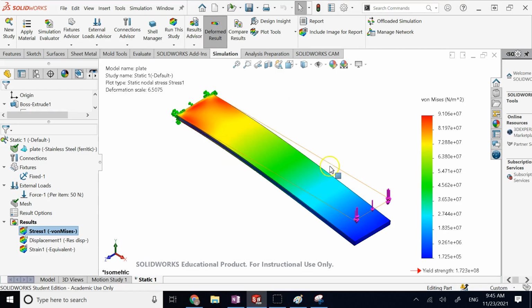So this is how the stress is going to be distributed in 3D. And you see the level of stress is below the yield strength, so we are still within the elastic region, and the small displacement assumption is valid, so we are good, especially for stainless steel, right? And these are the numbers, and this is, as I said, the distribution of the stress and so on. Now, another way to handle it is to, as I said, convert it into shells, which are like 2D elements, and then compare.